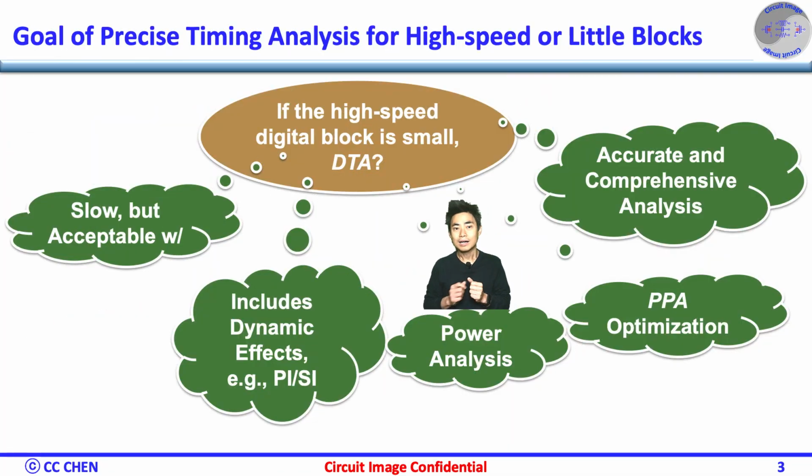Therefore, we are seeking a precise timing analysis for high-speed digital blocks, which may not have a great timing margin, but are small enough to handle a more complicated verification flow. Hopefully, the dynamic timing analysis, DTA, complements the STA by considering these dynamic effects, providing a more accurate and comprehensive analysis of the circuit's timing behavior and enabling designers to achieve better performance, reliability, and power optimization.